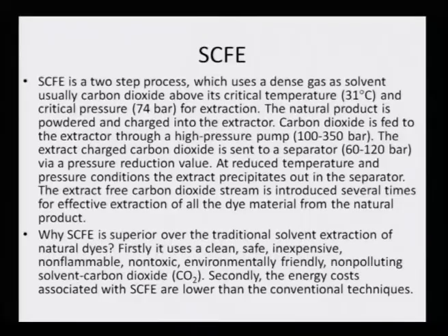Secondly, the energy costs associated with SCFE are lower than the conventional techniques. Because of the quick extraction process, the energy required for pumping the carbon dioxide is much less. One can complete this cycle of passing the liquefied carbon dioxide through the plant material, and then rarefying it, in a much faster manner, and maybe within half an hour the job is done.